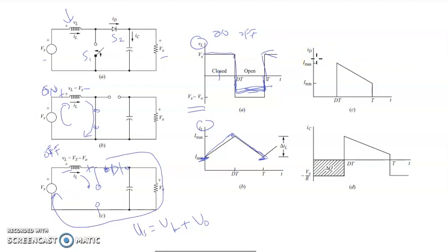Meanwhile, if you look at the diode point of view at the on and off state, when we switch on there will be no current through your diode, because all the current goes through the closed switch S1. But when you switch off, the pattern will follow the same as the current that flows into your inductor.